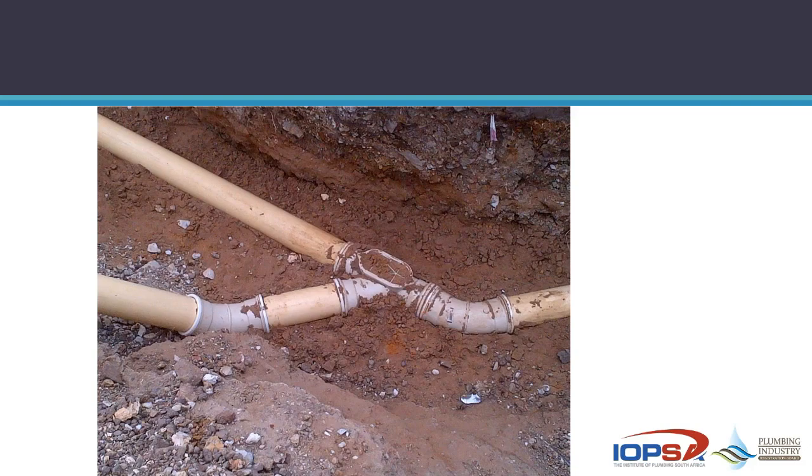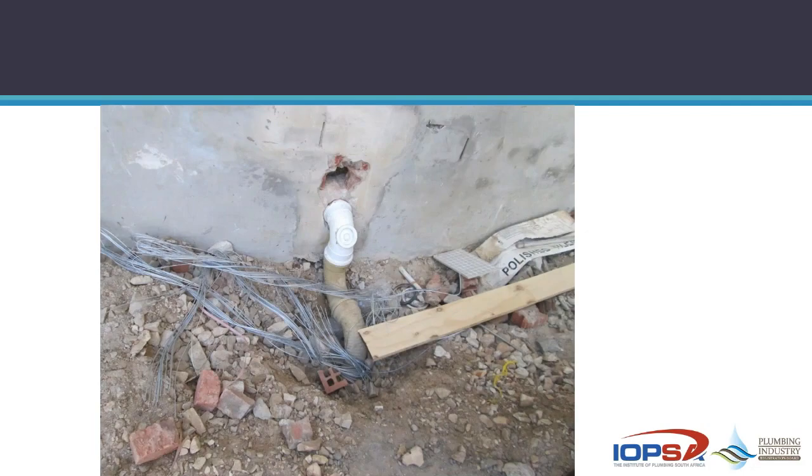So that had to be moved. Those are not 600 diameter. Those are just normal. You can see there's no difference between the S&V and the underground fitting. So good luck to the guy that comes along and does maintenance on an IE cover to start off with, instead of a stub stack, and then having to force his way through these two 90 bends and then end up in a 45 and a Y junction somewhere else. Not acceptable.